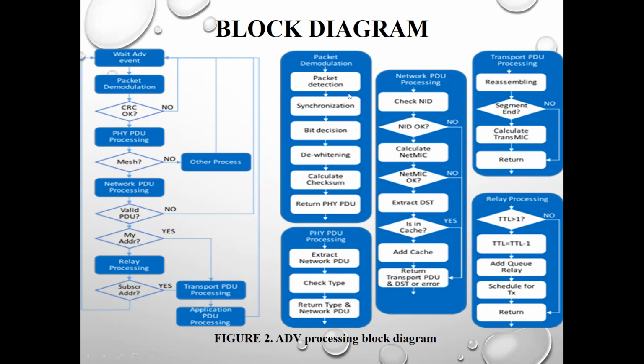Here you can see packet demodulation and all the steps it includes: packet detection, synchronization, bit decision, de-whitening, and PHY PDU processing, and all the steps it uses for network PDU processing.